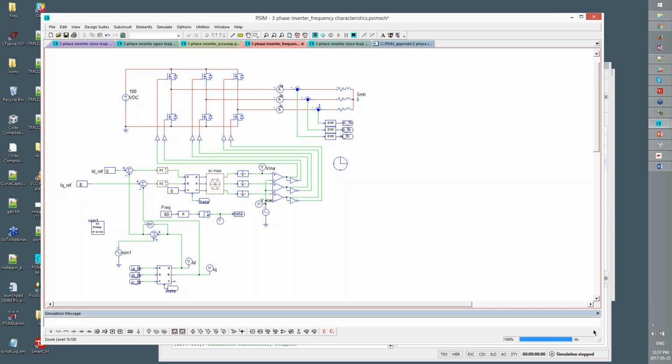The control code doesn't care where it's going. It's nice to run it in hardware-in-the-loop because we're not going to blow anything up if we discover any errors. Once we have this fully defined and we know that it's working properly, we can just plug it into the real thing right away. There are no intermediary steps, and I'm not sure how that can be accomplished with those other tools.